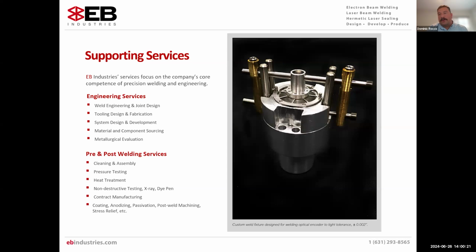EB will always offer a few certain advantages that laser just cannot duplicate. EB is much more favorable when welding crack-sensitive material. In particular, I think we're talking about dissimilar metal welding, certain chrome moly steels, things that we just would not really have a chance at if we were performing traditional pulse laser welding.